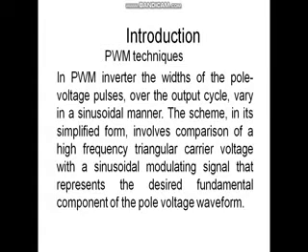There are many classifications of inverters. Based on the input supply, they are classified into single phase and three phase inverters. Based on the connection, they are classified into series and parallel inverters. In all kinds of inverters, we use some control techniques. The motto is to control the output voltage of the inverter. In inverter circuits, we use pulse width modulation techniques to control the output voltage.